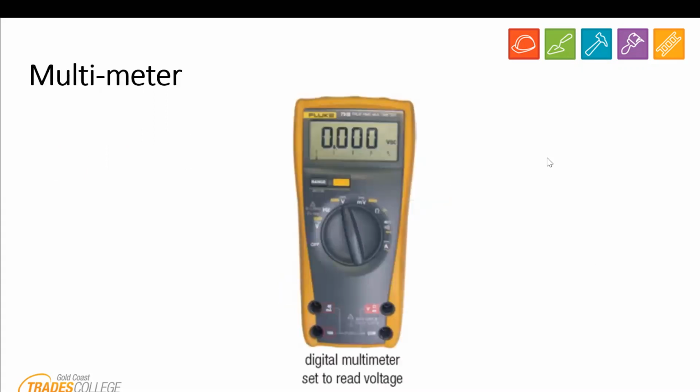Okay, move on. So this is your multimeter. There is a type of tester that isn't included in this PowerPoint, and that's the one I would suggest if you guys are looking at buying testers: your LED type of tester. In your voltage video from YouTube, the guy explaining talks about the types of testers he suggests getting, and I agree with the choices he says there. I don't have them in here, but again, an LED is a good one, because it relies on the power from the supply to light it up, as opposed to the one you're looking at on my screen, which uses the battery to show you the reading.